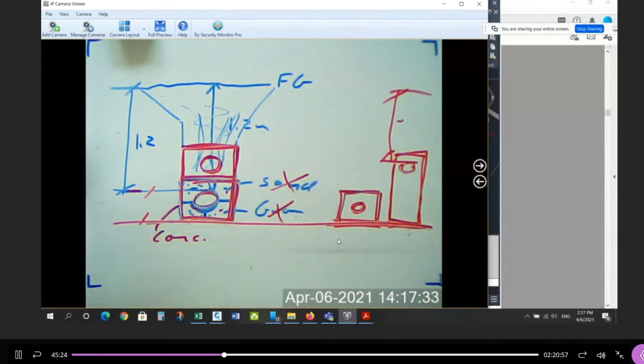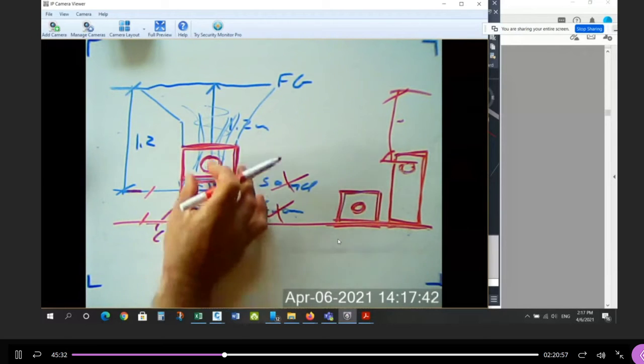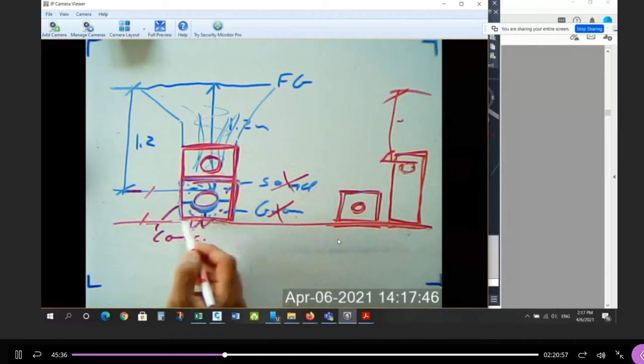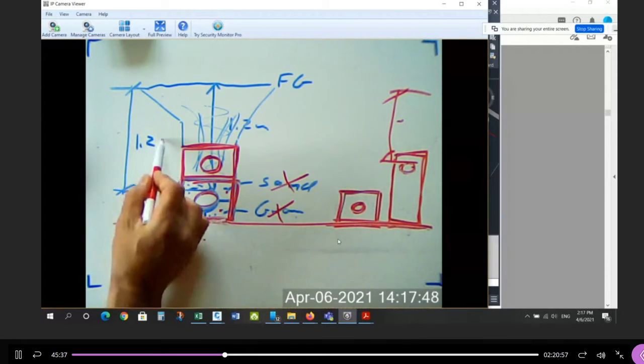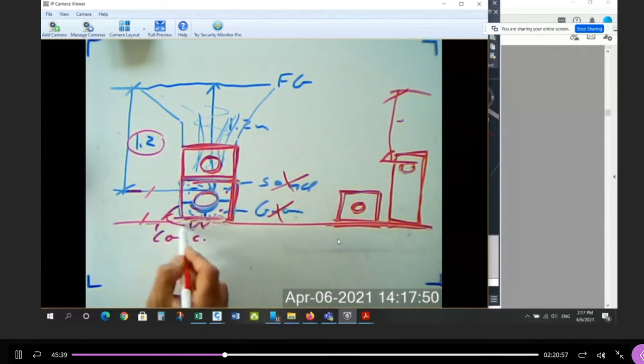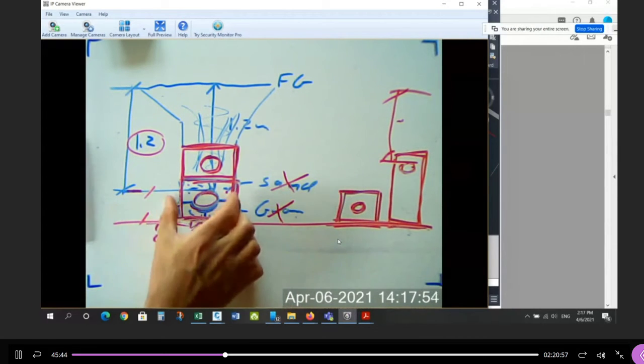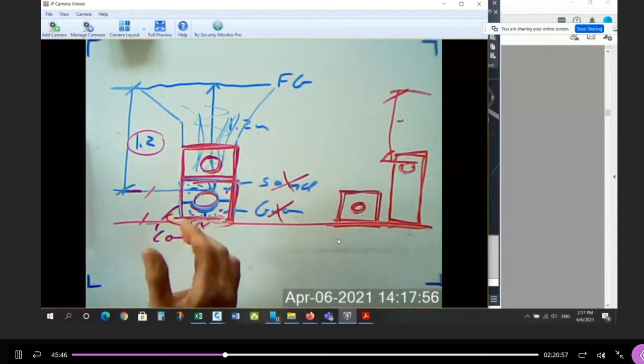And the problem with frost is when the ground freezes, water expands and it pushes things up, right? So if water gets underneath this and expands, it'll move the pipe up and down. So it'll freeze and then thaw and then freeze and then thaw. If this is always below 1.2 meters cover, it never freezes. It's frost protected. Okay?